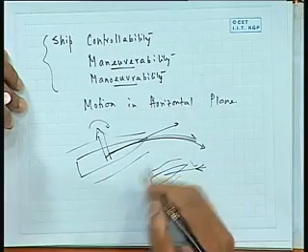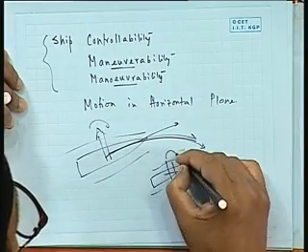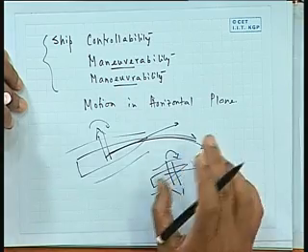Then the flow goes various ways and there will be a different set of pressures, and therefore there will be some kind of force and some kind of moment acting on the ship, and it is that which will cause the ship to turn. In other words, the only mechanism that you have to cause force on a ship which is not restrained is fluid forces, because of the way the flow is going past it. These are the forces that will cause it to turn. You give a rudder, you change the rudder, and because of that the flow past it develops a different pressure system, and that is why there is a force.